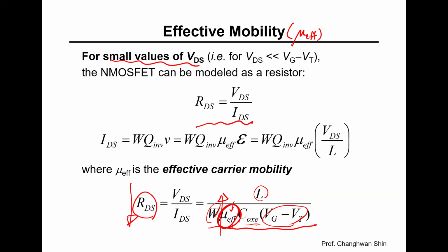Okay. So the effective mobility differs from bulk mobility that we have studied in device physics, because carriers in the inversion layer experience additional scattering mechanisms. Think of it like driving on a highway versus a crowded city street. Your average speed, which corresponds to the mobility, is much lower in the city because of more obstacles and interactions. So in MOSFETs, three main scattering mechanisms affect mobility.